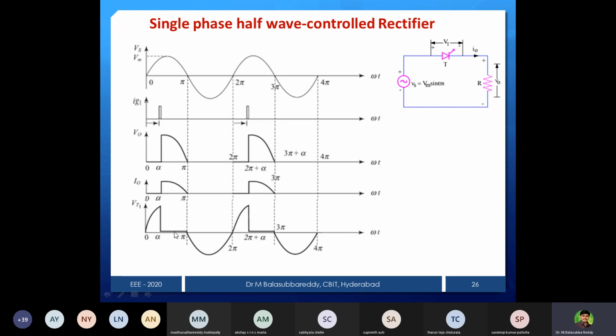And the small gap I mentioned, whether you want you can use it, otherwise you can make it 0 only. That gap is the voltage drop across the device when it is conducting, 1 volt or 2 volts, 1 to 1.5 volts normally. We don't usually show that. Normally you can keep 0 also. Strictly speaking, there is a small voltage drop. You can make it 0.